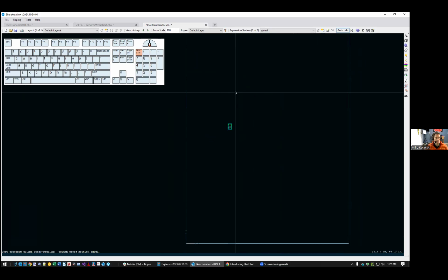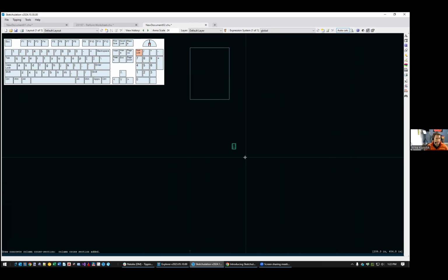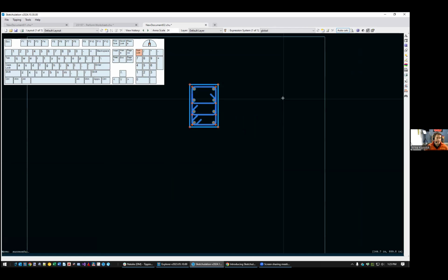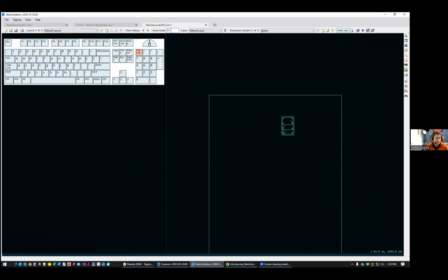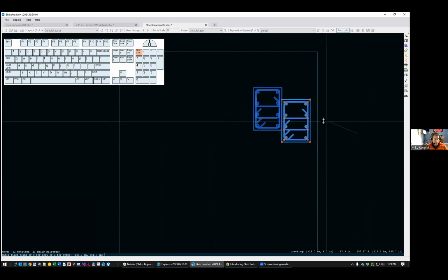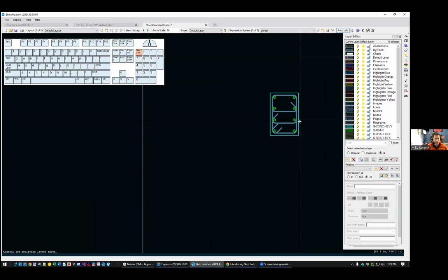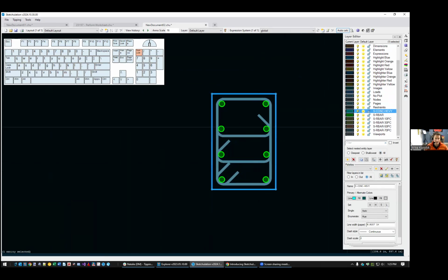So we're going to adjust our annotation scale accordingly. I'll try 24. That's typically a decent scale for this kind of detail. I'll move my column over here. It's still too small, so I'm going to go to 16. A couple of things to notice right away is that the ccolumn command created some layers. I'll show that briefly. In our office, we have various layers that we use for concrete and rebar. Conc heavy is for when you're cutting through the concrete, you get this heavy line, and you'll see that heavy line has a width of 0.157.